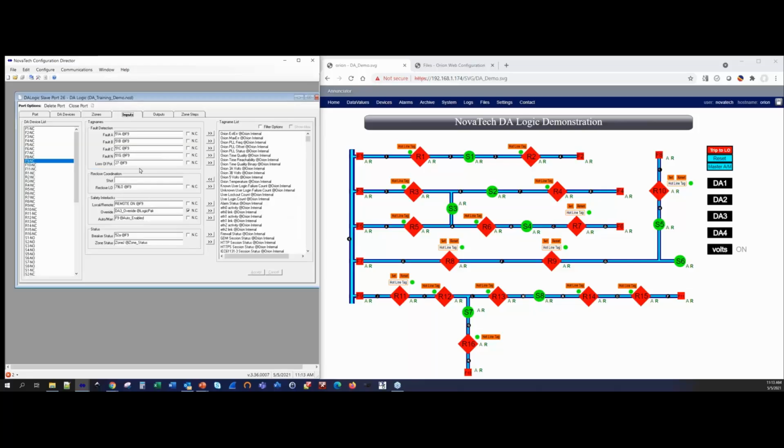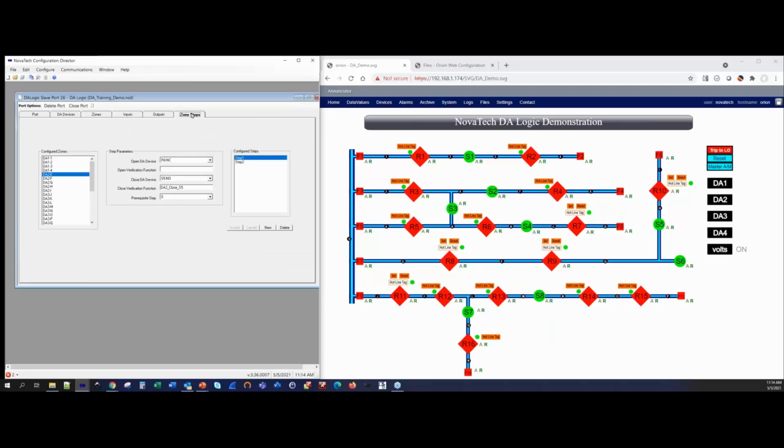So we are going to get a loss of voltage at feeder 1, 3, 5, 7, and 9. That voltage is looking at the bus voltage, and when they all see a loss of voltage at the same time, that indicates that the condition is true, and whatever the zone steps are for the bus outage